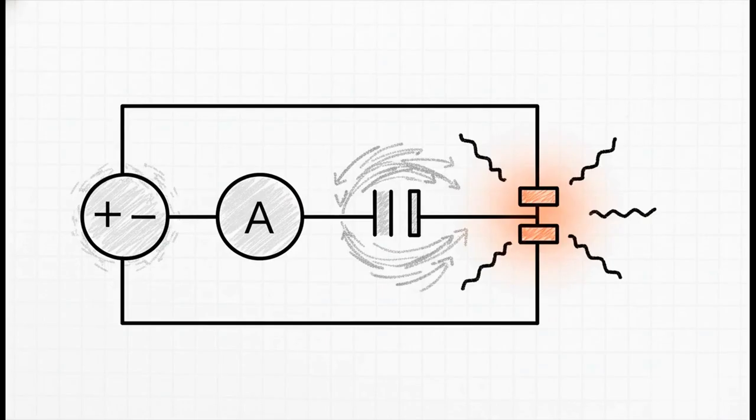Okay, so we switch over to circuit B. Now we're applying a known voltage and measuring the current. This completely solves our high resistance problem. But you knew there was a catch, right? If you use this setup on a low resistance device, you have to pump a huge amount of current through it just to get a voltage you can actually measure. And all that current creates heat. Enough heat, in fact, to literally change the resistance of the very thing you're trying to measure. You end up chasing your own tail.